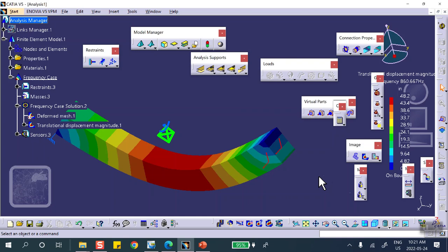Okay. So let me go and change my restraint here from a roller to a pin. Remember I said that the instructor sometimes drew both pins for you, and okay. Let's go ahead and do that. So I have two choices. I can just start fresh, or I can clean this one. So I'm going to clean this one. Deactivate.